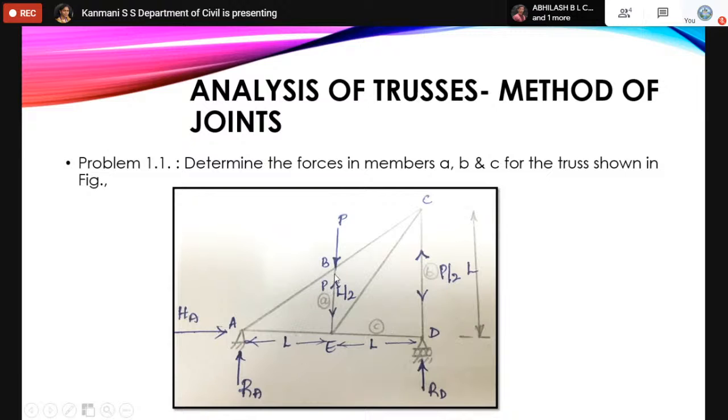And if I come to joint B, wherein I need force A, joint B has 2 sets of collinear members, nothing but 4 members joined at joint B, where force P is collinear with BE and force AB is collinear with BC. When 2 sets of collinear forces are joining at one point, what happens? The forces in the collinear members are transferred to the other member.